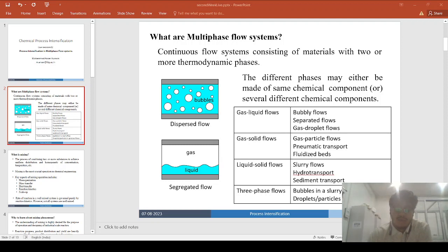micro scale. Now, what happens in the microreactor is as the size decreases, the net available surface area increases. For the heat and mass transfer, if you see Fourier's law and Fick's law, they both contain that the flux is directly proportional to the specific surface area that is available for the heat or mass transfer. So you multiply the concentration gradient or the temperature gradient, which are the driving force, with the net available surface area for the mass transfer or heat transfer to happen.